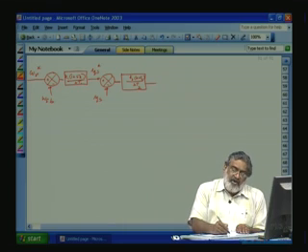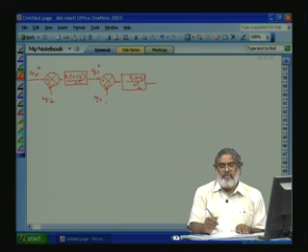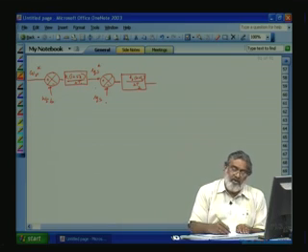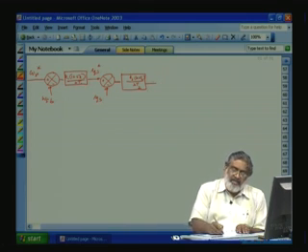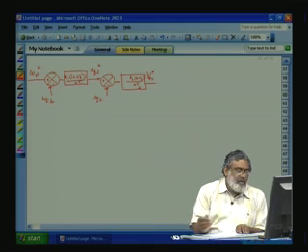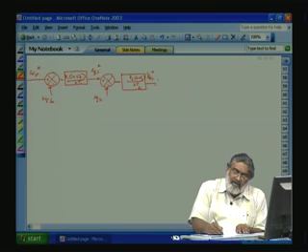But if you want to control the space vector PWM, then we require the voltage reference. So here we will have IQS reference and IQS feedback, then one more PI controller. This output will give our VQS reference. Okay. This vector we will give to a PWM converter. So converter has to be, or inverter.